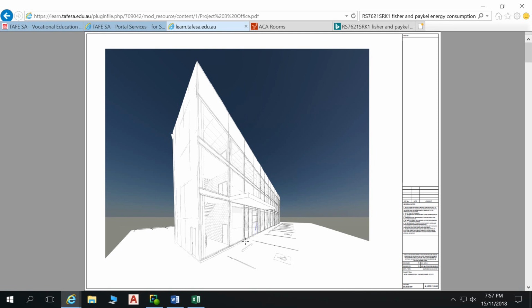So let's say we choose a particular type of cladding system, and we explore the idea of having a timber facade that doesn't meet FRLs. We might be able to use it in one situation and not in another.